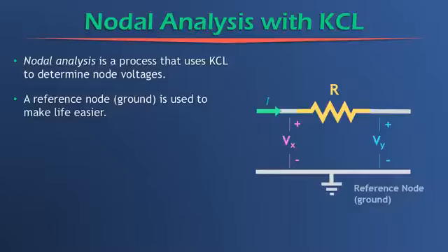Now, how do we choose which node we want to make our reference node in a circuit? Well, rule of thumb is to pick the node in your circuit with the most connections to it. That'll make your life a little easier.